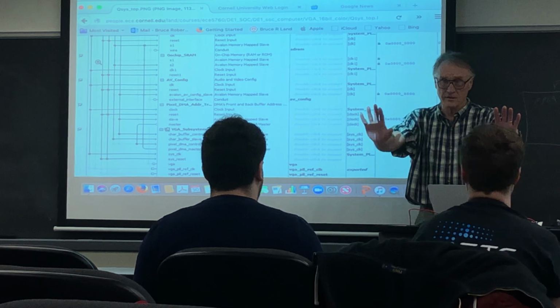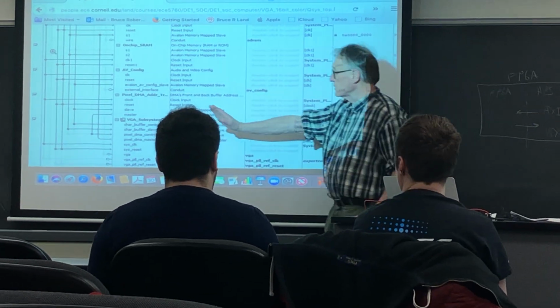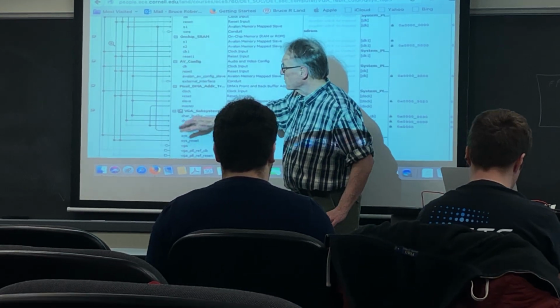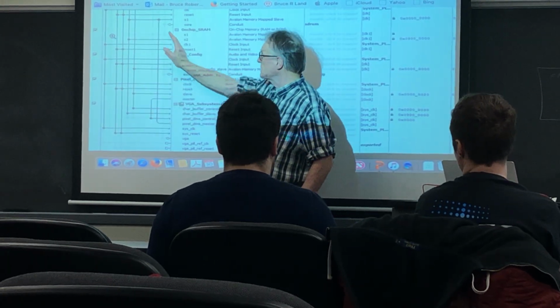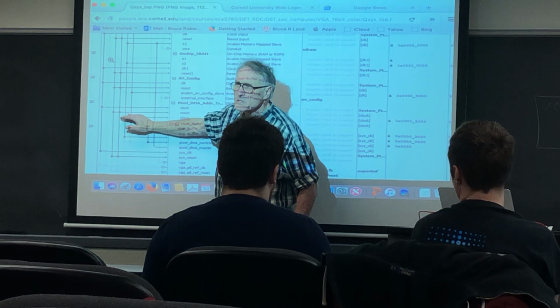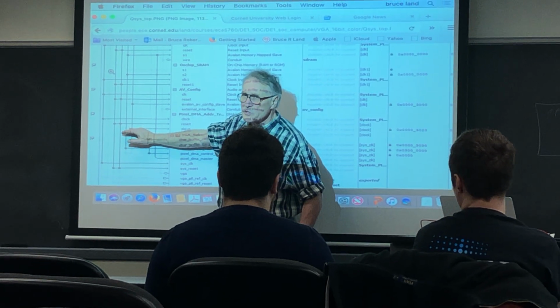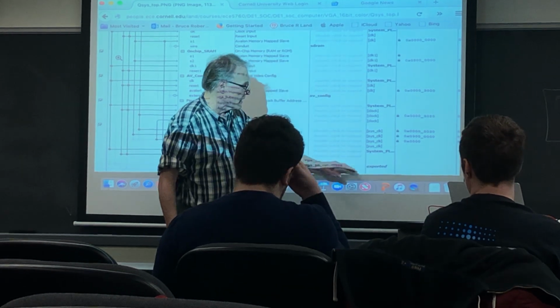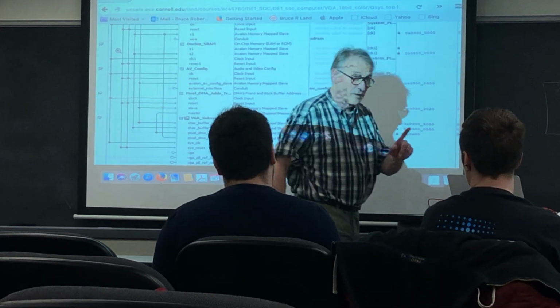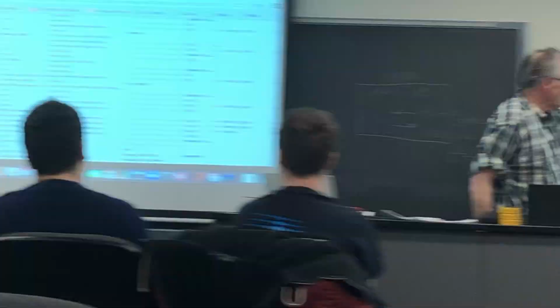So there's 2 interfaces here. There's going to be the Qsys interface that allows modules to talk to one another, and all of the Verilog wiring which is done to wire these together is invisible to you outside of the module which is generated by Qsys. And there are then the signals which are exported, which will be visible to you in your Verilog.